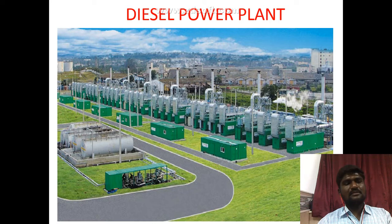The working medium has constant specific heats, and the working medium does not undergo any chemical change throughout the cycle, right? The compression and expansion processes are reversible and adiabatic, and there is no loss or gain in energy. The kinetic and potential energy of the working fluid are neglected, right? So these are all the assumptions we have to make in the analysis.